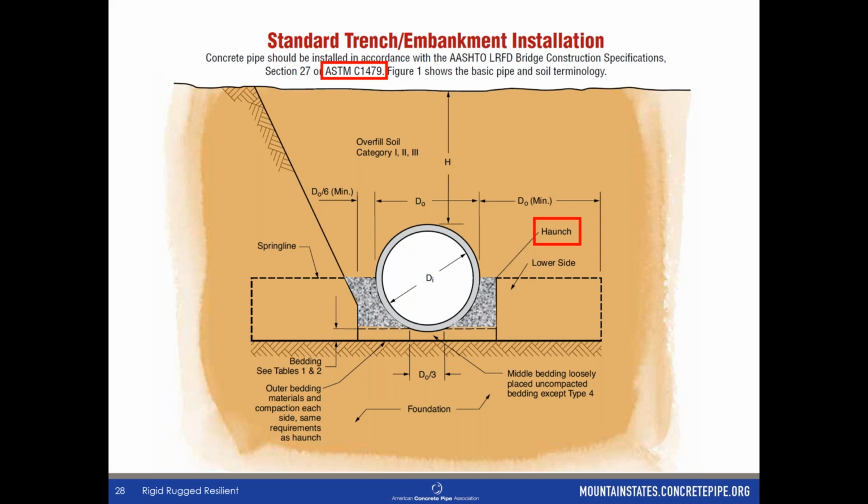Now, understand that, again, in the spirit of being conservative, I spoke with the American Concrete Pipe Association head technical engineer. He's vice president over engineering, and he pointed out to me that when we do these designs for the fill height charts, we design these knowing that it's going to be hard to get good compaction under there. So they have a conservative measure in there to say we have anticipated there would be voids and gaps under there. So we're trying to be as conservative as possible because we don't want to see our products installed incorrectly and fail. And we put in some of these safeguards in there.